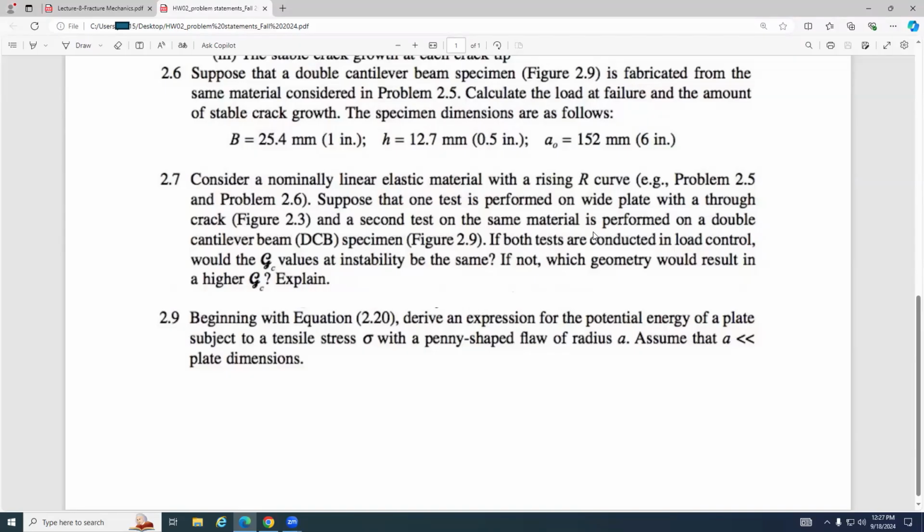I need to have two, because any crack will have two surfaces. Keep this in mind. So as a result, this is Ws, then I can have dWs over dA, where A is the area, which equals 2 gamma s.